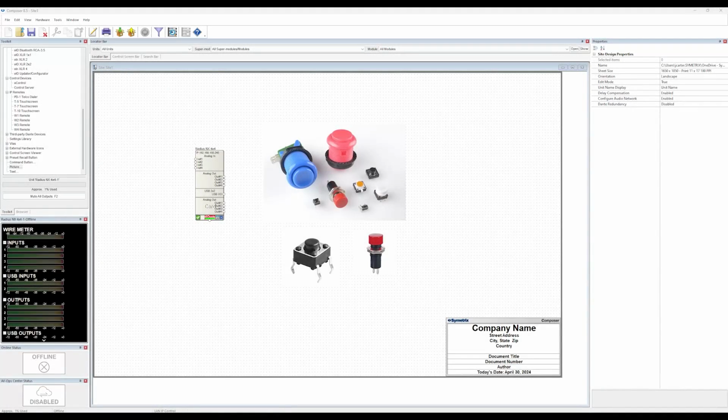Mute buttons in Composer are essentially latched buttons, toggling on and off active and inactive states. However, a client or end user may request the use of a momentary style, physical button to toggle a mute. This can be programmed in Composer using some simple logic modules.